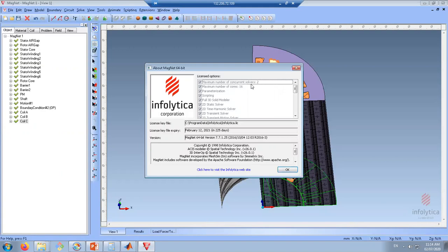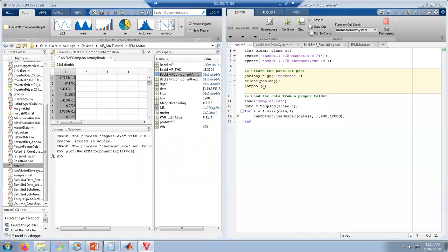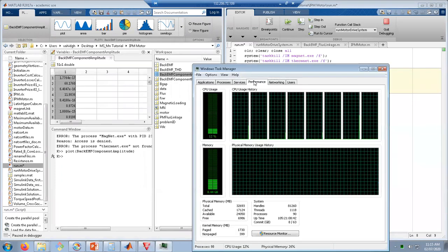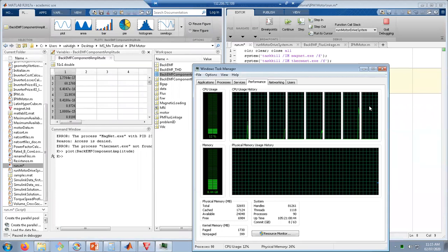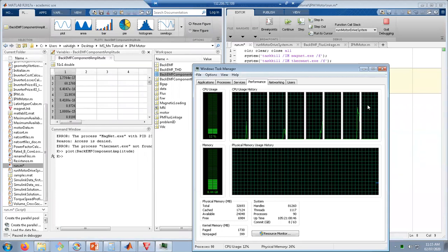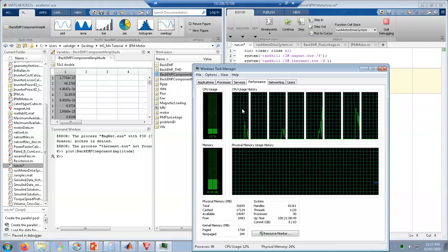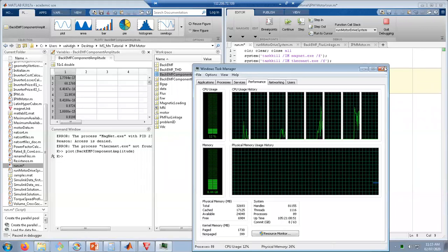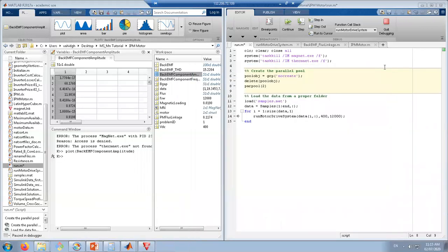This is our limit. If the license gives us the capability of using more concurrent solvers at the time, obviously we can increase this number to 3, 4, or whatever can be managed by your CPU. Here I have 8 threads, so I won't recommend using all the threads at the same time, because as you increase the number of concurrent solvers, it will get slower.